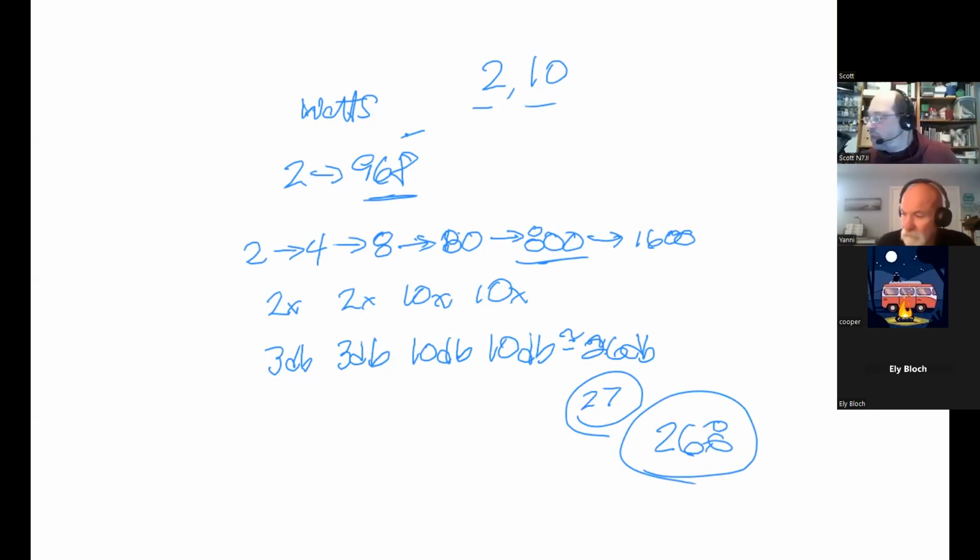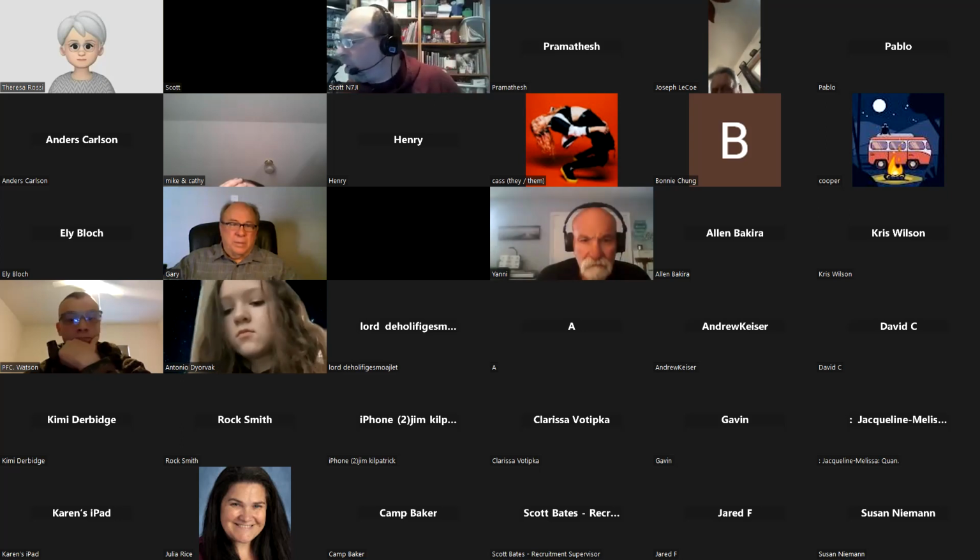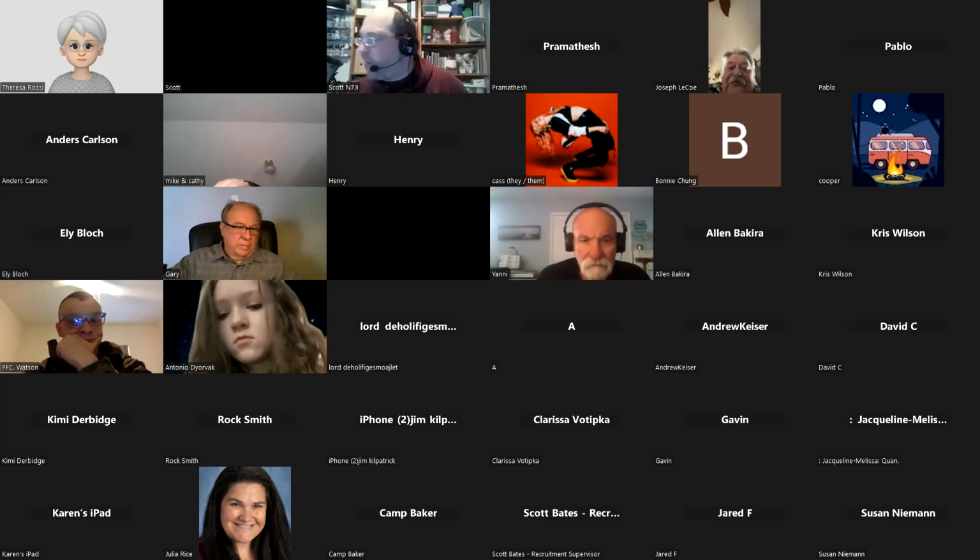So what's the goal here? The goal is to determine the gain in decibels? Yep. Because the main reason for this is, let's say you buy an amplifier, or you're going to specify an amplifier to purchase. An amplifier will typically not be specified in watts. It will be specified in dB gain.